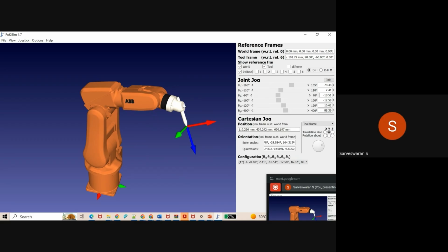From here to here you will get, for example, a final torque of 5 newton meter, and the same thing you have to apply for motor selection: select a suitable actuator to overcome this torque. So suppose you consider a 5.5 newton meter torque servo motor. Similarly, we apply the same criteria to joint 1.